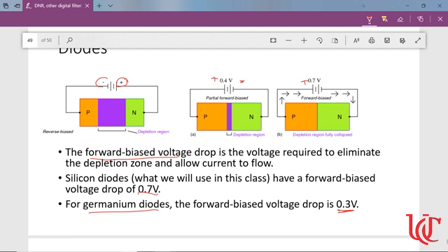So if I increase this because I applied positive to this side and negative to this side, and then if I flip the voltage that I apply to this, yeah, it will change pretty quickly. Like if I apply something different to that, they will go back to it. This was only building up because I had an applied positive voltage here. The second you detach a diode from its voltage, it's going to build up only its natural length of the depletion region, because charges want to move back based on diffusion from that.